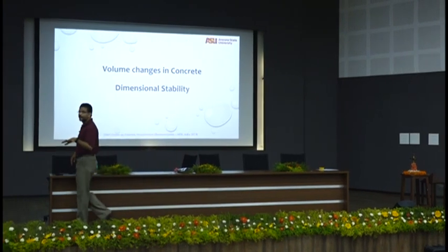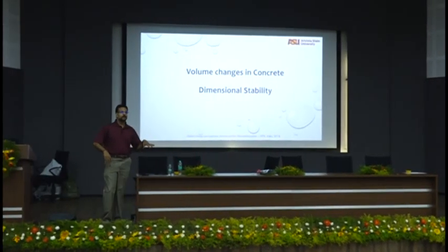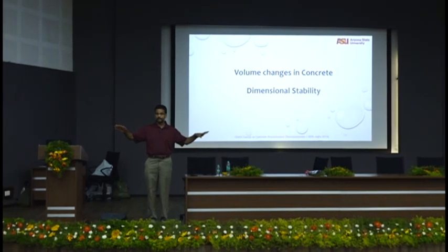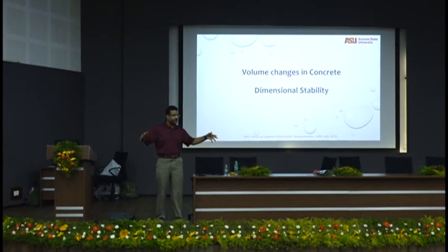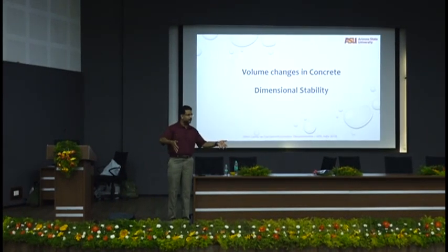You are not building a concrete structure to be floating in air. If it's a pavement, it will be restrained by the base and the sub-base. If it's a beam, it's restrained by the column. If it's a column, it's restrained by the foundation and the walls on the side. So every concrete structure at any given point of time is always restrained.